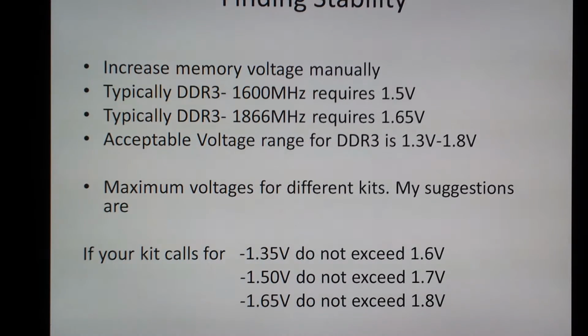I was able to obtain that XMP parameter by running 1.71 volts. I was able to overclock my memory from 2400 megahertz to 2666 at 1.78 volts. So that's just a little example of my case with 2400 megahertz memory rated at 1.65 volts.